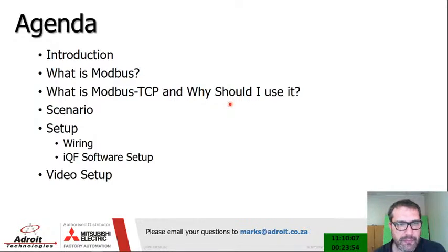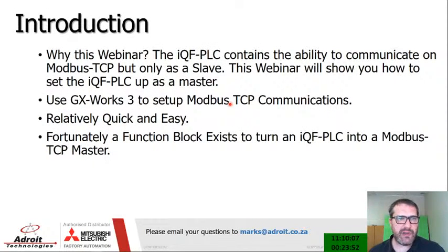Okay. So guys, why did I do this seminar, or webinar should I say? The iQF PLC contains the ability to communicate on Modbus-TCP, but only as a slave. This webinar will show you how to do the setup of the PLC as a master. That's a Modbus-TCP master. As always, we'll use GXWorks 3 to do the setup. It's relatively quick and easy, and what makes it easy is that there's actually a function block which exists on this so that you can get it up and working.